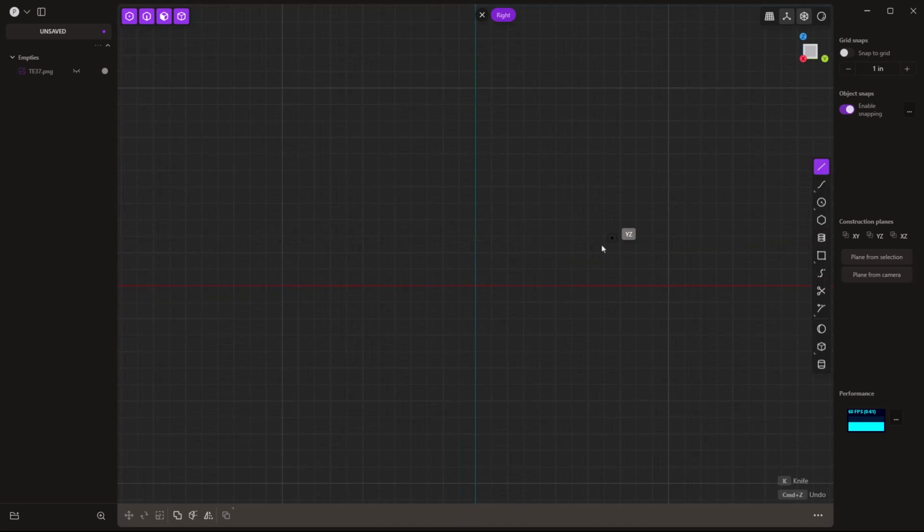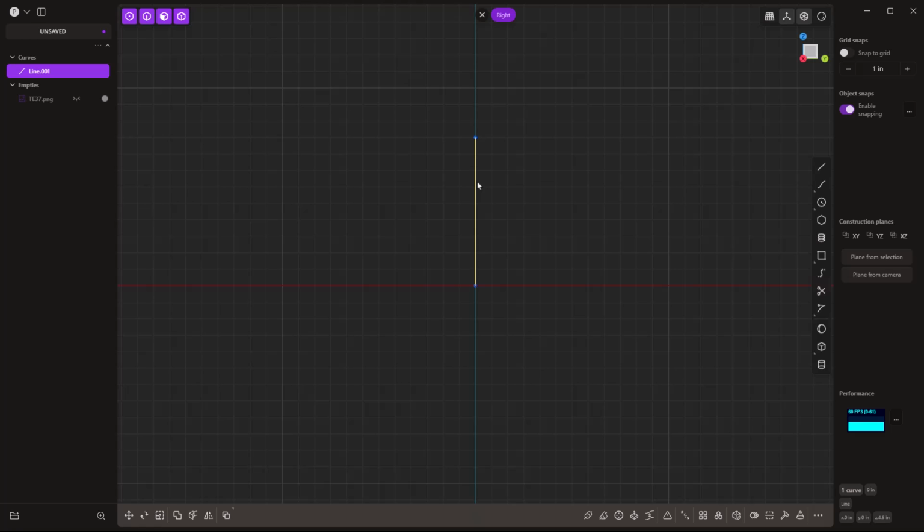Then I'm going to start by creating a vertical line from the origin, hit tab, and enter 9. This is a radius value because we're dealing with only half of the rim profile. We're going to go up 9 inches, and that'll give us our essentially 18-inch rim. Then I'm going to do a horizontal line. I'll hit tab, and we're going to make this rim 8 inches wide. You can make it as wide as you want. You can put the back spacing wherever you want. But now we've got a reference for the diameter, or the radius really, and then a reference for the width.